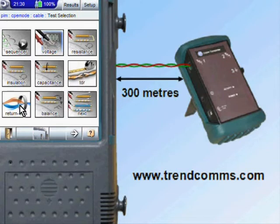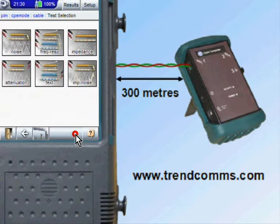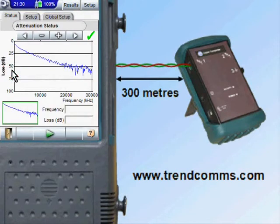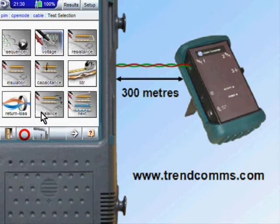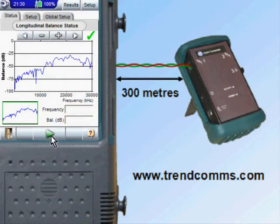And there are many transmission tests which can be used to assess the performance of the copper at frequencies up to 30 MHz. This is the attenuation of the line, measured using the transponder as the far end transmitter. Let's run the longitudinal balance test.